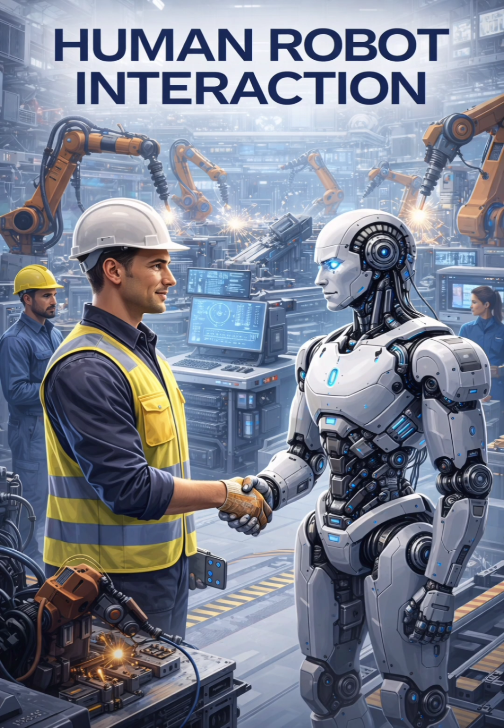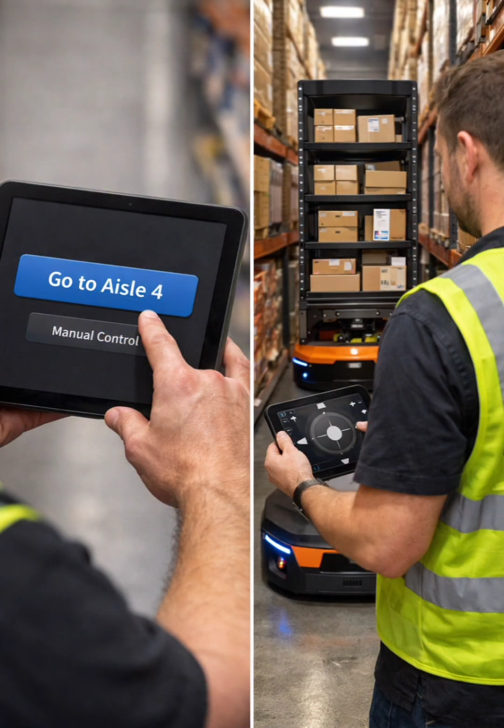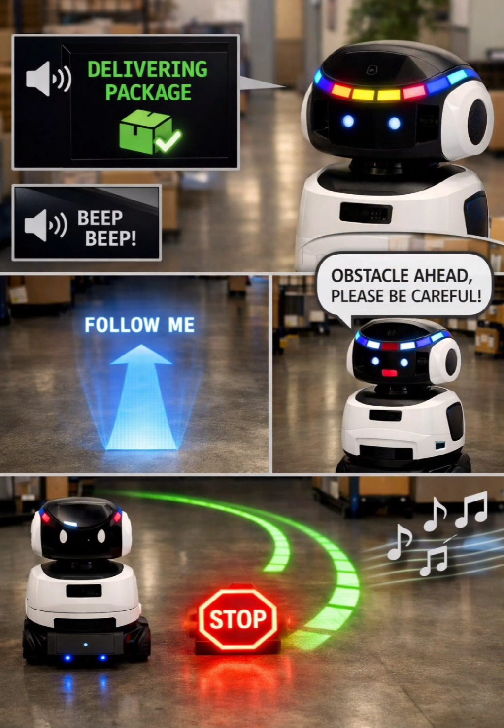Human-robot interaction is the part of robotics software that manages how humans and robots communicate, coordinate, and share control. It is required because robots operate around people, and the system must be understandable, predictable, and interruptible, especially when autonomy is uncertain. HRI software typically has three functions. First, it provides input channels for humans to specify goals or intervene. This can be a touchscreen, joystick teleoperation, voice commands, gesture input, or a remote control interface. For example, a warehouse operator can tap "Go to aisle 4" or take manual control to reposition the robot in a tight space.